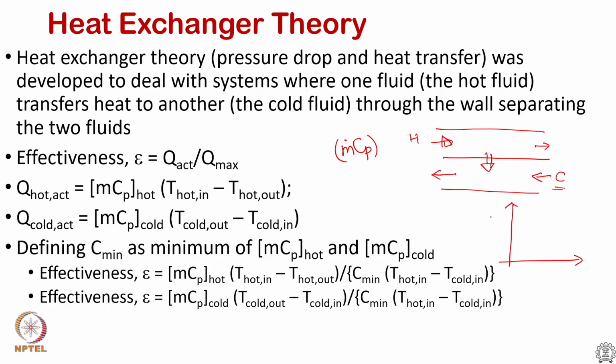that the temperature profile in a heat sink typically, because the heat sink is made of copper or aluminum, very highly conducting material. Typically the materials used for heat sinks are aluminum, copper, and so when it is dissipating heat, the solid side thermal conductivity is so high compared to the fluid side, which is air typically, that now you have a situation where the solid side can be treated as if it has a temperature profile. This is temperature and this is x,